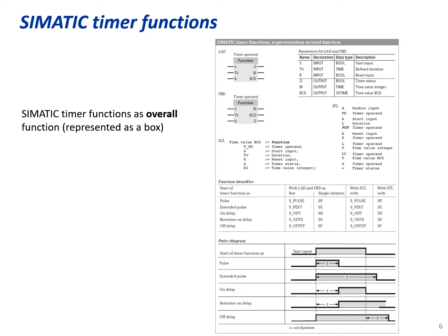So see that there is also one reset signal here, and this is a time value. The second one is the time value, or defined duration, and the R is the reset input. So for the retentive timer, we have to reset it, otherwise the output doesn't go to 0.